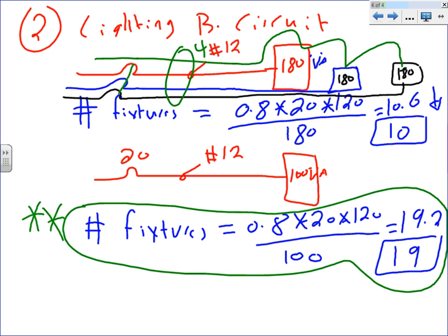Any questions, guys? I thought that would give you at least, as you start circuiting, Spencer, you're going to start moving with the circuits. When we circuit, guys, you're going to be doing the power circuiting, always circuit with 3-phase, always in the back of your mind: phase A, phase B, phase C. So 1, 3, 5, or 2, 4, 6, as you start circuiting, because you can balance the load. If I have 3 circuits in this room, you put circuit number 1 here, circuit number 3 here, and circuit number 5 here. I'm guaranteed phase A, phase B, phase C with a common neutral, good to go.